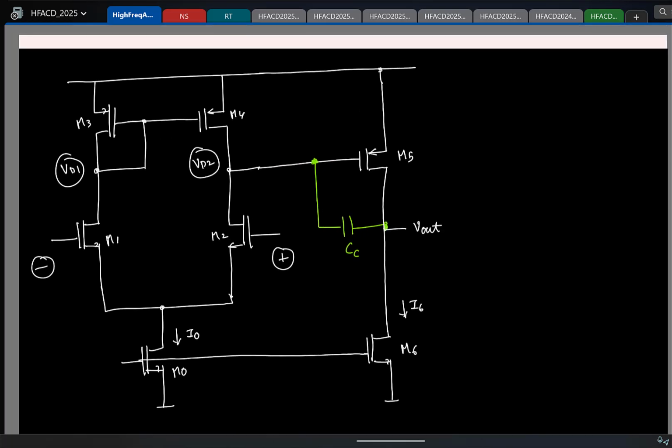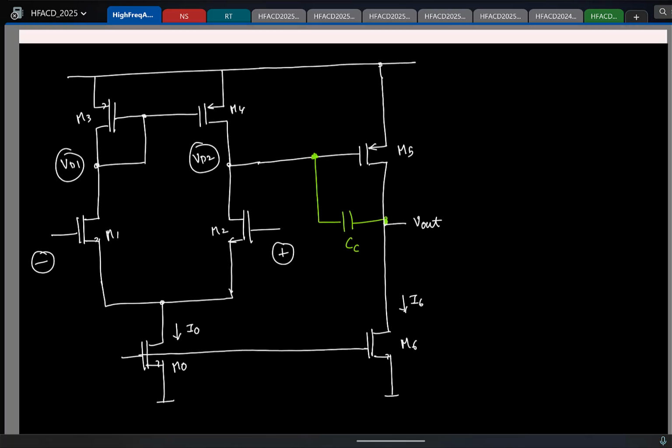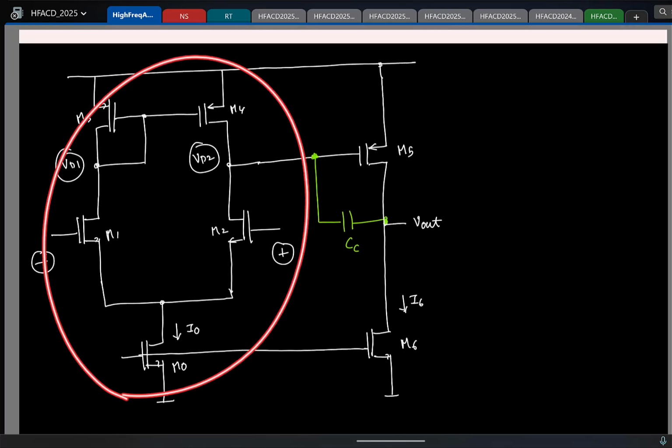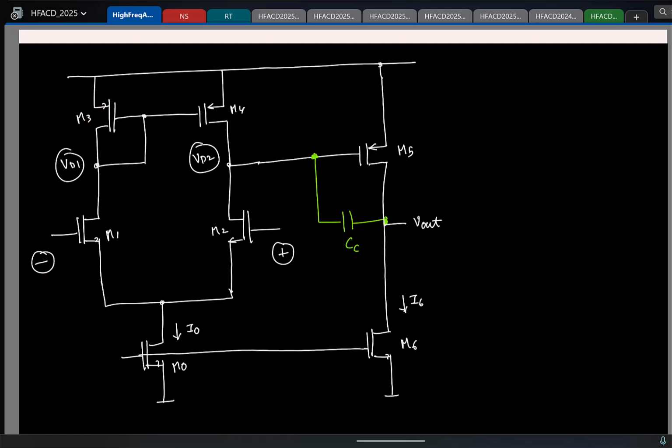Okay, cool. So now we'll do the same thing as we have been doing. First, let's see what is the operating point so that we know things are in saturation. Then the small signal properties. And operating point, at least for the first stage, we already know what is the deal. So if I apply the same voltage here, we know what are the two voltages at this node. No confusions. So what can you say about the output here? What is the DC potential at the output?